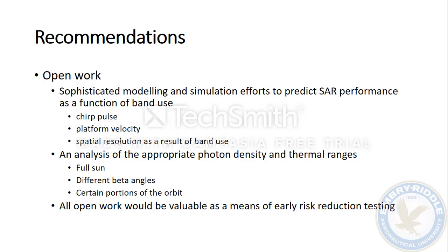And also, it's just really good to get analysis of the appropriate photon density and some of those thermal ranges by doing some thermal distortion testing based off of full sun, different beta angles, different portions of the orbit, things of that nature.